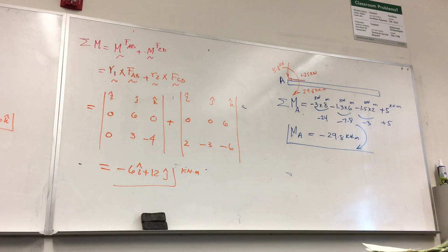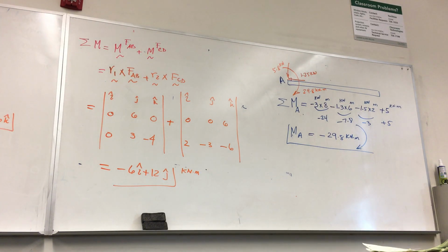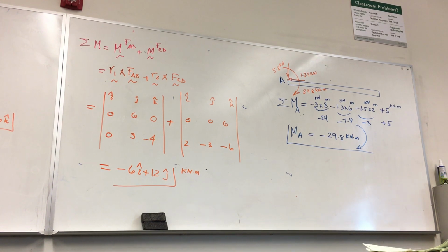Which means then that by moving these forces to point O, you have to add also a moment there, which is a component of 6 kilonewton meter in the negative direction of X. And you remember, we show moment with a double-headed arrow. So this is 6 kilonewton meter and a component of 12 kilonewton meter along Y. This is 12 kilonewton meter.